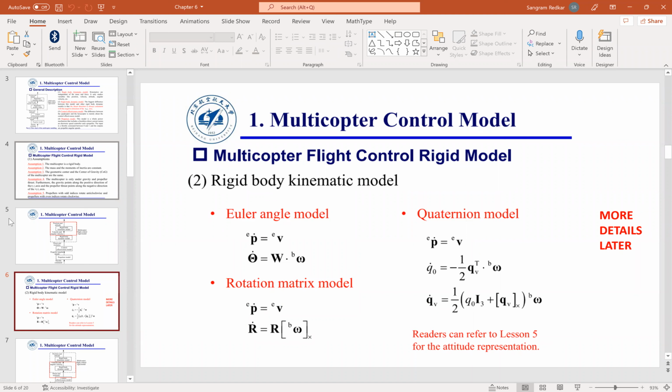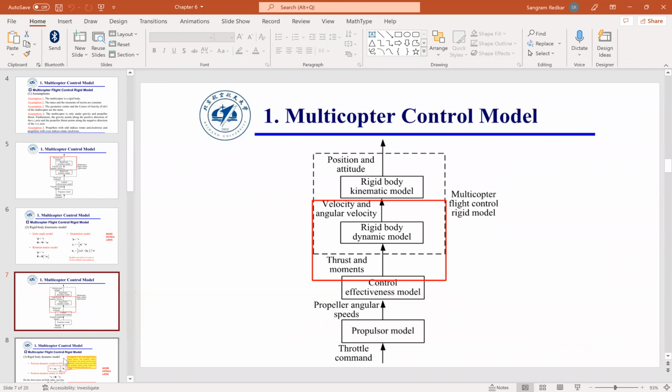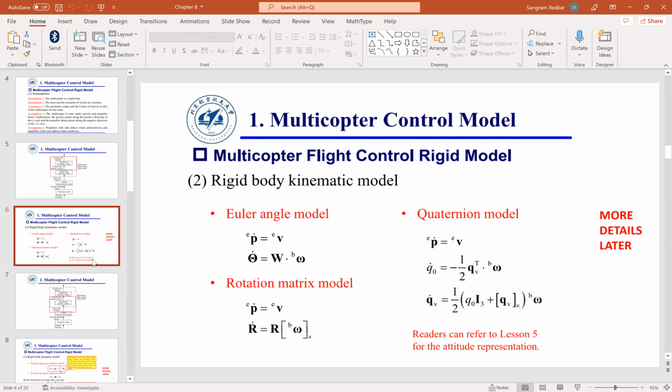Now, the next part I want to talk about briefly is, once you solve the kinematics equation, once you know the position, once you know the velocity, what next? Then you look at the masses and the inertia properties and incorporate something called the rigid body dynamic model. Last slide. So understanding the entire dynamic model, all we need is Euler's first equation and second equation, and since that is the same in rotation, this first equation is ignored.